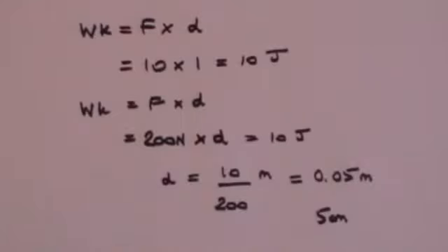So you can see what's happening. You're getting a very large force compared to the one you've exerted, but it doesn't travel up so far, and you'd have to push down a long way if you wanted to get a significant lift. Nonetheless, hydraulics can take a small force and amplify it to a larger force, but as I said, the price is that the small force has to travel over a much larger distance than the larger force will.